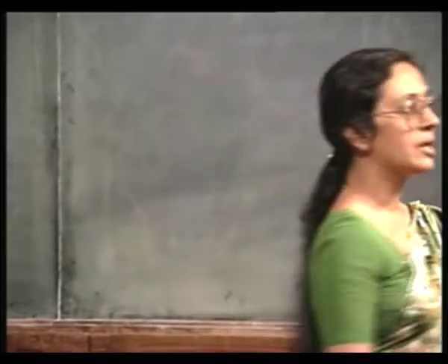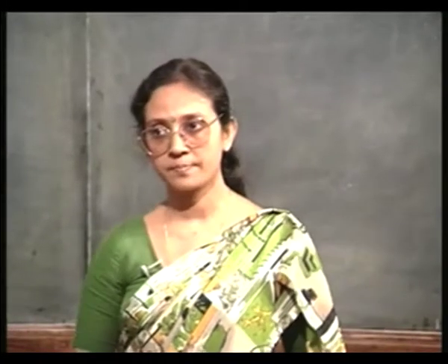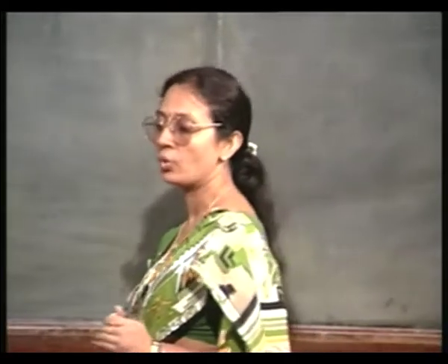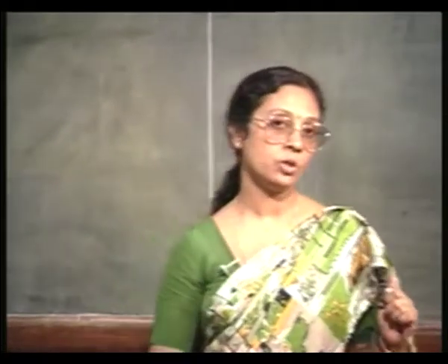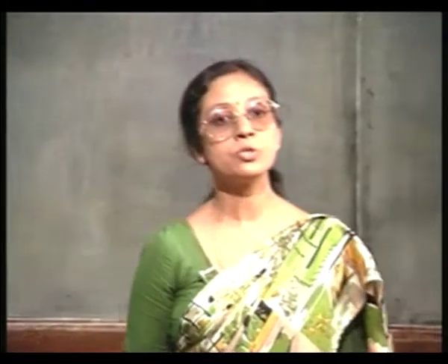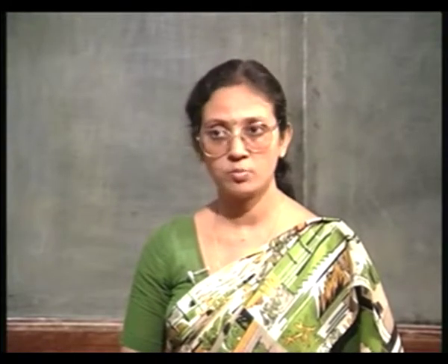That is why I am classifying that as a subclass of the interstitial dopant, even though the dopant atom will be found both in the substitutional sites as well as in the interstitial sites. Okay. And the examples of such dopants are copper, nickel and gold. Particularly gold is very important, because you know gold is used sometimes as a deep impurity in silicon, and its movement is like that, both substitutional and interstitial, but the movement is primarily governed by the interstitial movement.